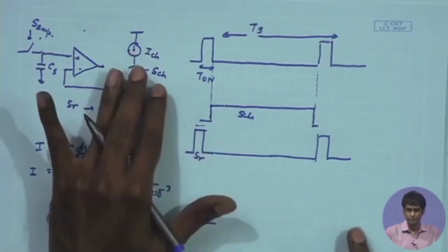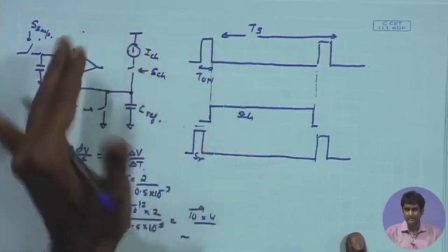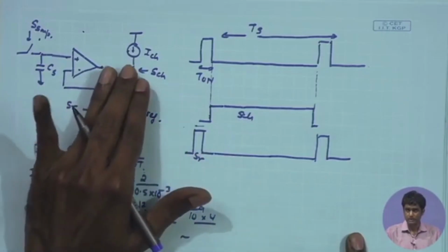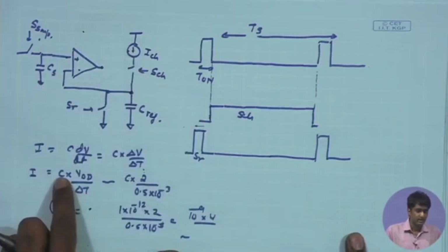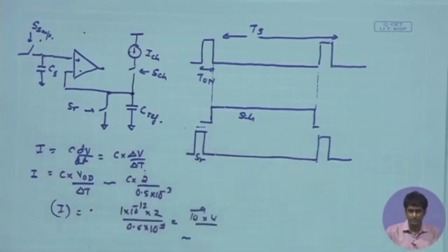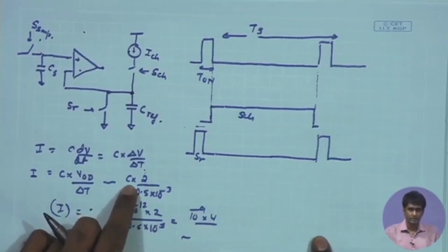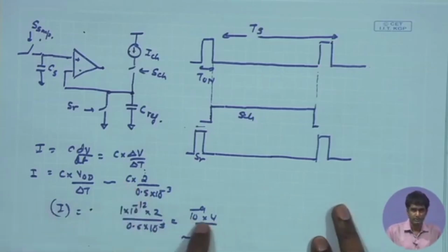So generally, when we use this kind of subthreshold current source, there can be some mechanism through which we can calibrate them, and even after fabrication we can set them close to the desired value. But the control becomes more and more challenging if they are operating in the deep subthreshold regime. Therefore, that may mandate a larger value of C over here. So if we want to have 100 nanoampere, that is 0.1 microampere of current, we can see that will require at least, say, 10-20 picofarad of capacitance over here. So if I choose, say, 25 picofarad of capacitance, that will lead to around 0.1 microampere of current, which is relatively safer.